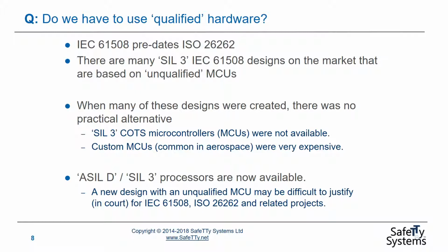And some people suggest, well, there are designs out there that clearly don't have qualified components in them. For example, the International Safety Standard IEC 61508 predates ISO 26262 by many years. And there are many SIL 3 IEC 61508 designs on the market that are based on unqualified microcontrollers. SIL 3 in IEC 61508 is essentially equivalent to ASIL D in ISO 26262. So these designs are based on unqualified microcontrollers.